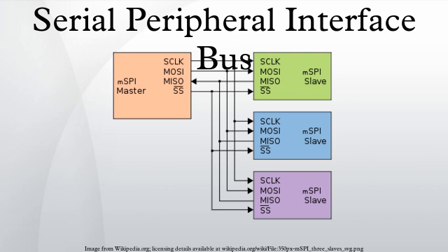Logic analyzers: when developing and/or troubleshooting the SPI bus, examination of hardware signals can be very important. Logic analyzers are tools which collect, analyze, decode, and store signals so people can view the high-speed waveforms at their leisure. Logic analyzers display timestamps of each signal level change, which can help find protocol problems. Most logic analyzers have the capability to decode bus signals into high-level protocol data and show ASCII data.